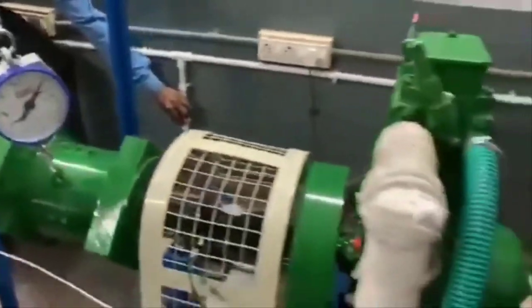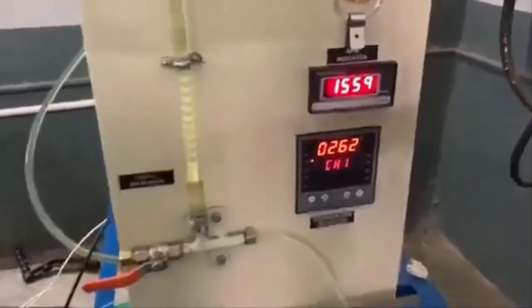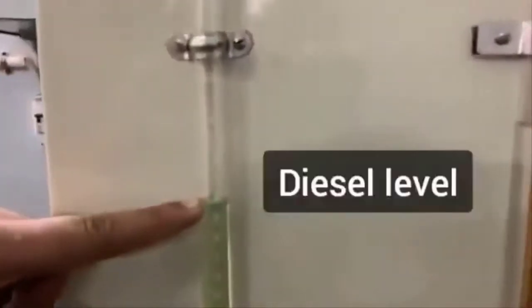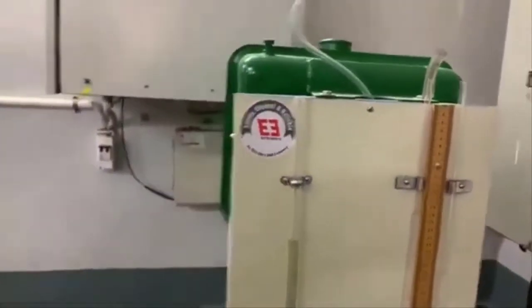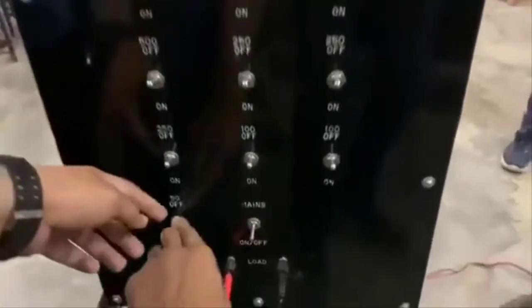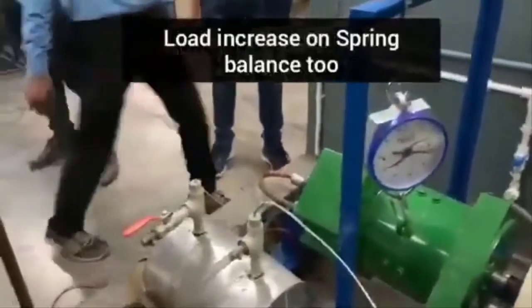First we are checking that the water flow is coming and is perfect. Thereafter we will start the experimental setup, in which you can see the RPM is now showing on the tachometer, and you can also see the different temperatures. I will show you what these temperatures are during the calculation. First we have already marked the diesel level in the burette, and this is the main setup in which we are connected to the load bank. First we will check whether the load is on or off. Thereafter we will start our load bank. First we will apply 1 kilowatt, that means we are applying it in a successive manner. After applying, we will let it stabilize again.